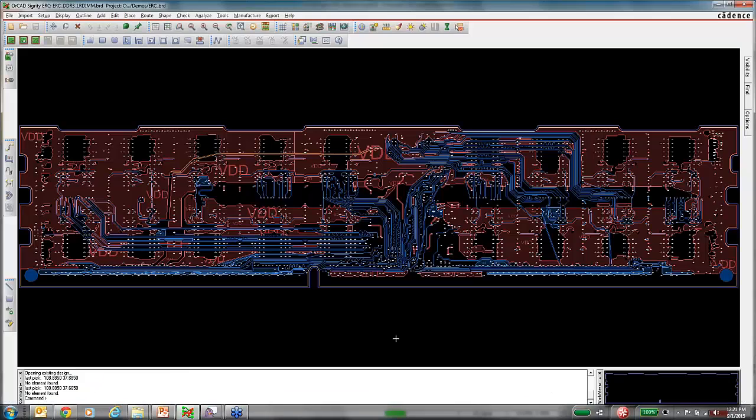So I'm going to open up PCB Editor. And what I have here is basically a registered DIMM circuit or registered DIMM board. This is a low-power DDR3 design. And so in my layout here, maybe I've done a bit of routing. This particular board, I believe, is complete, but it doesn't necessarily have to be in terms of the signals that I'm looking at. But here I'm looking at my particular design, and I want to go and run some ERC checks.